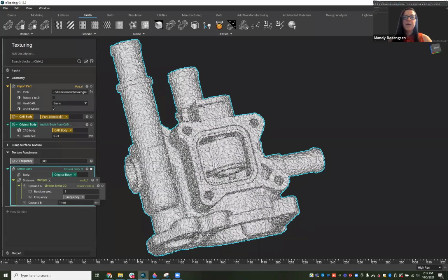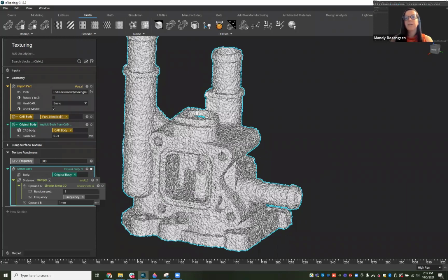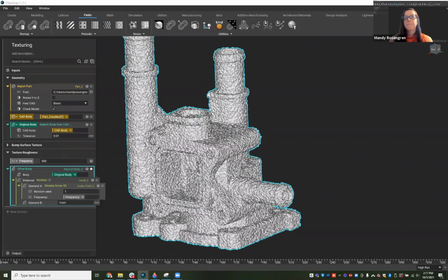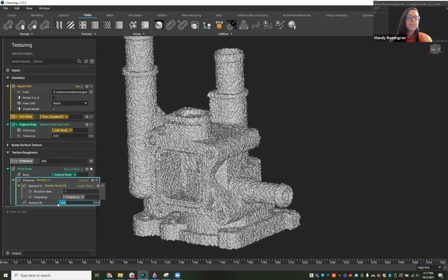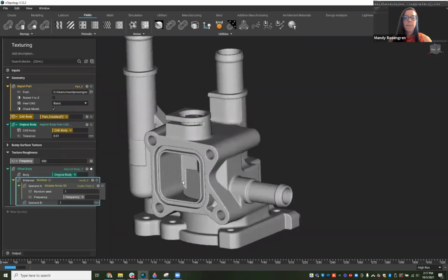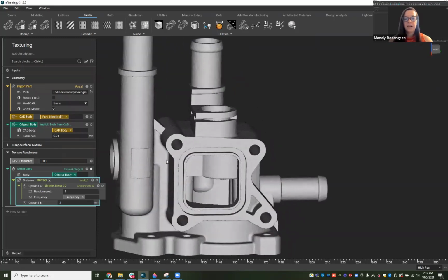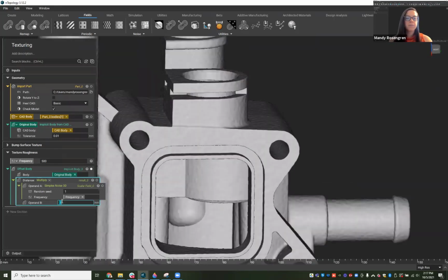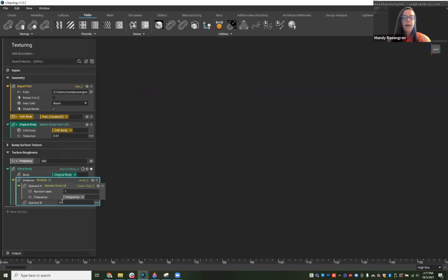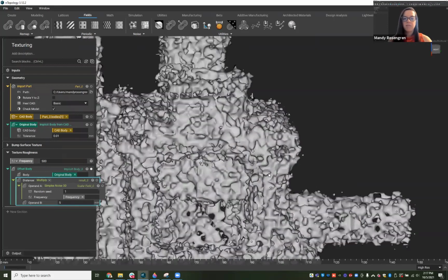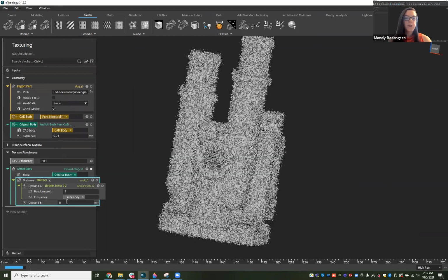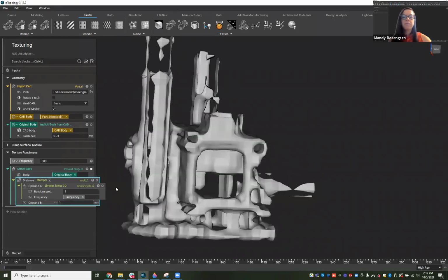So we're just offsetting it by that simplex noise 3D. We can also change that amplitude by changing how much we're multiplying this by. So if I made this multiply by 0.1, we can see that that roughness is a lot. It's not as large in those certain areas. We've made it a lot smaller. We can make this 5, and we're seeing a lot of noise. So you can play around with that as well.